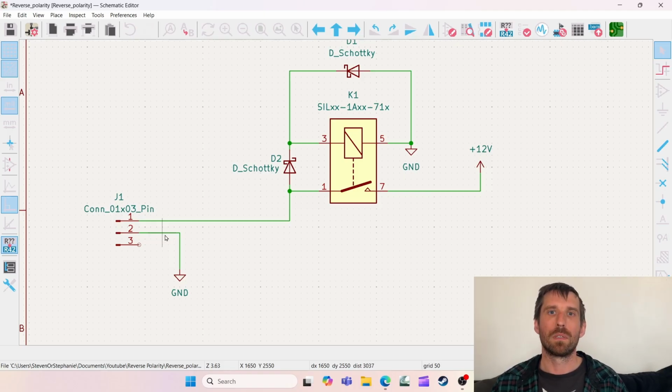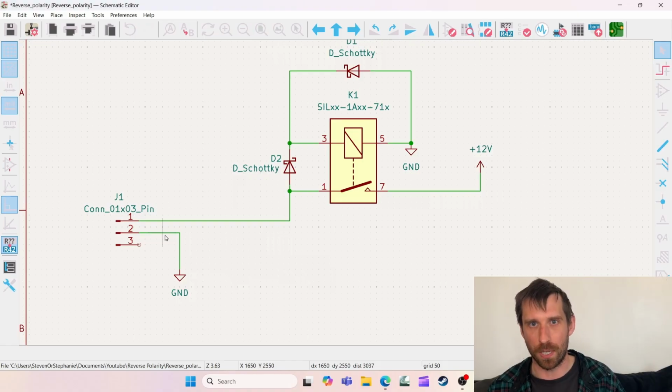Now, what if you outsource production of your cable assemblies? Well, they will do a lot better, but they will still mess it up. Now, depending on how bad a reverse polarity situation is, which you should test, all the possible faults in your product. But I can tell you, sometimes it doesn't happen. I've seen it.